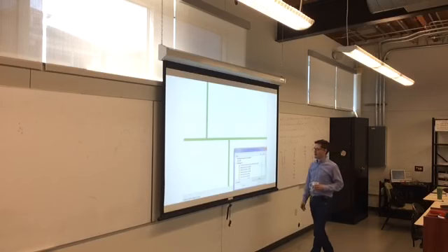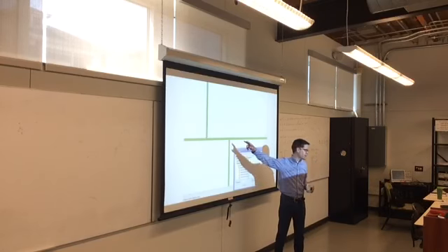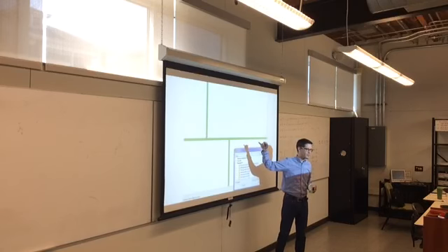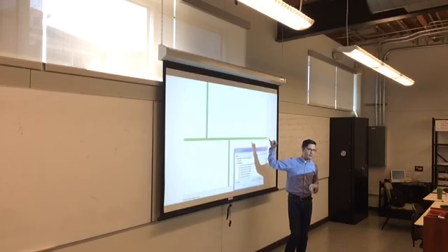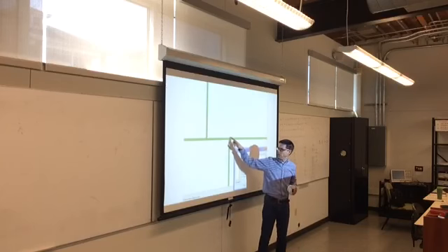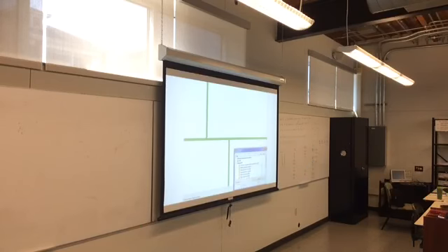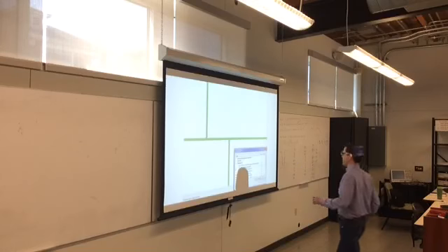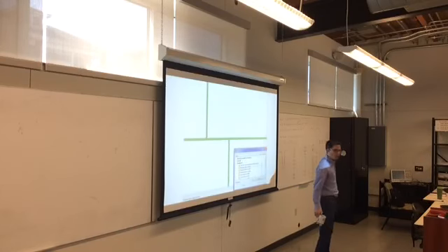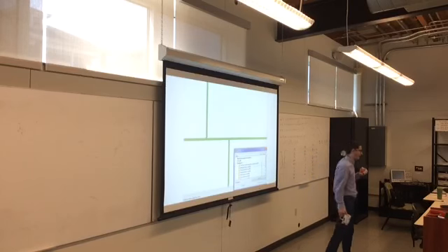One thing you do want to check warnings for is stuff like this. What you want to ask yourself is, are these wires actually connected? These wires in the diagram are not actually connected, even though they overlap, because there is not a node here. When nets are connected, you'll get a little green dot, a little green node. You'll go to wire it up, and you'll say, oh, I have these warnings, it's not connected. And you'll visibly look at your diagram and say, well, that looks connected. But if you drag one net away from the other, they'll rip apart because they are only overlapping. They are not actually connected.